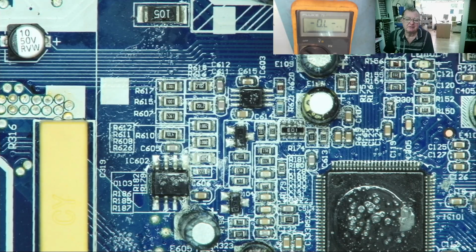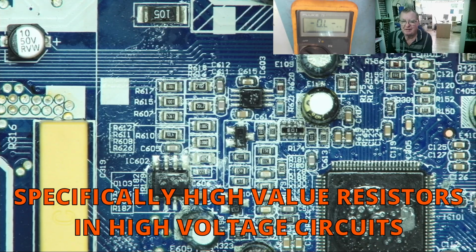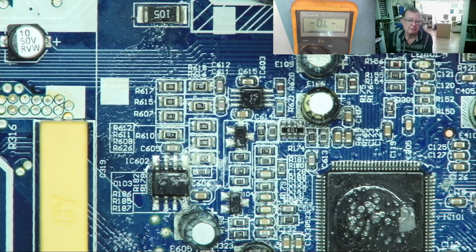About the only caveat to that is if it's got an inductor coil across it. Okay, so that's how you should take readings on resistors in circuit and what they mean. So failure: the most common resistors to fail are either high value resistors, which go open circuit or higher than they should, and low value resistors, which tend to burn up.